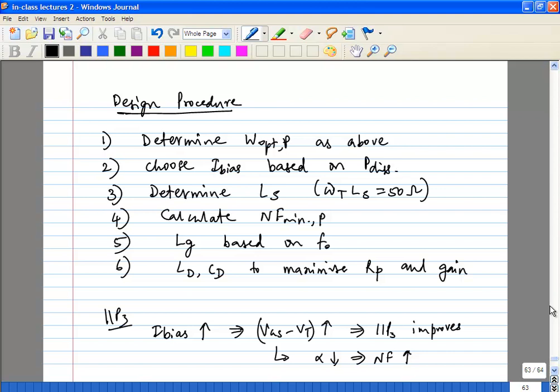But it's a low noise amplifier. You're designing for low noise, right? We just spent the last two to three weeks designing the LNA based on two-port noise and minimization of the noise. Otherwise, it's just a complicated common source. If you take any random common source, it will definitely have a much higher noise figure.